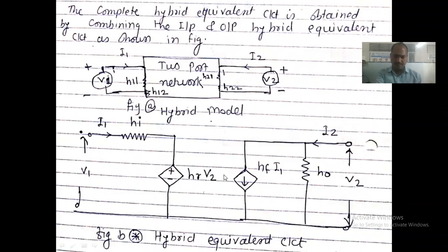Okay. The same we have to write as the part of the output circuit, right? So for that output circuit, we know that I2 equal to H21 I1 plus H22 V2, right? For the second term, H22 V2, we have to write first, right? V2 is the input applied. H22 indicates that it is the ratio of I2 upon V2. So that's why it is taken this way, right? Opposite to that of resistance. It indicates H22, which is multiplied by V2, okay?